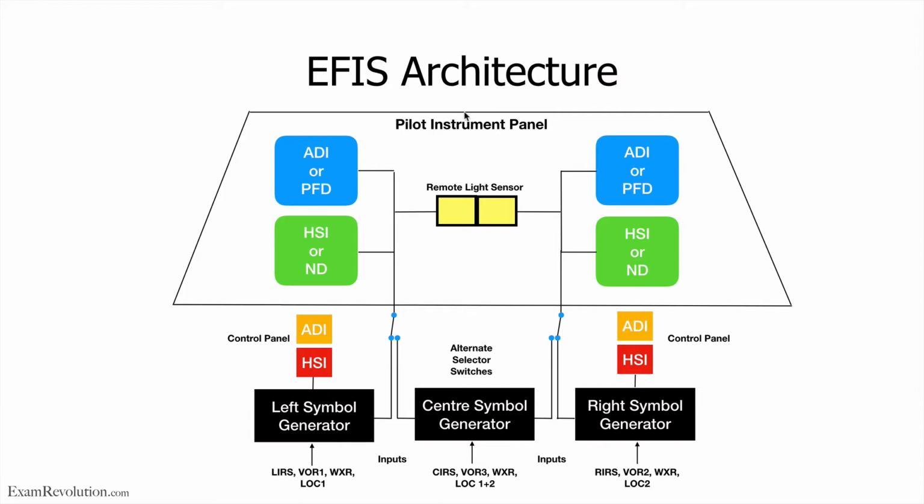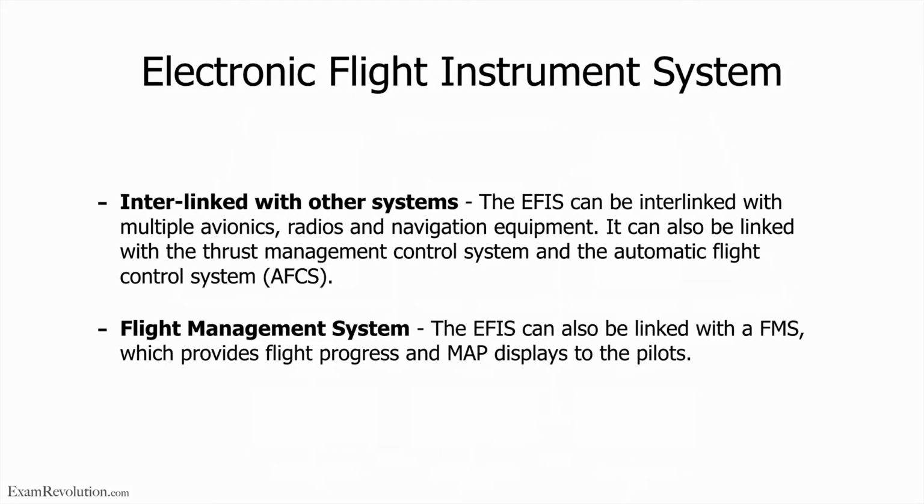So the EFIS is just this system over here, and the FMS is like the brain of the aircraft connected to these things. This is not the brain of the aircraft. This is purely just an information system, right? It just displays information to you. That's all it is. There's no brain or processes or mathematical equations or anything like that involved when it comes to the EFIS system. Okay, that's important to understand.